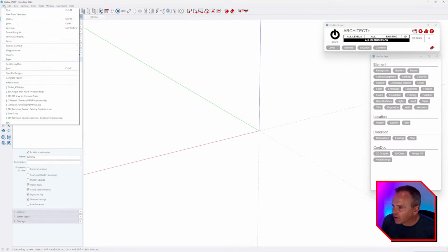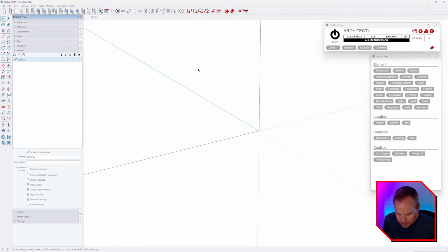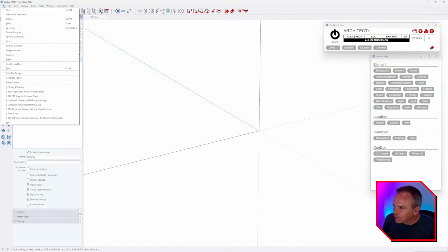All right. So I'm going to go to File, and let's see. All right. So any project that I'm working on, especially an exterior project, so really any architectural design project, any renovation I'm working on, I like to geolocate it. When you add a location to your model, you're going to get accurate shadows. You're going to get accurate terrain and aerial imagery. So we're going to use the add location feature, set this thing up, and then see where it goes from there. All right, so File, and choose Add Location.